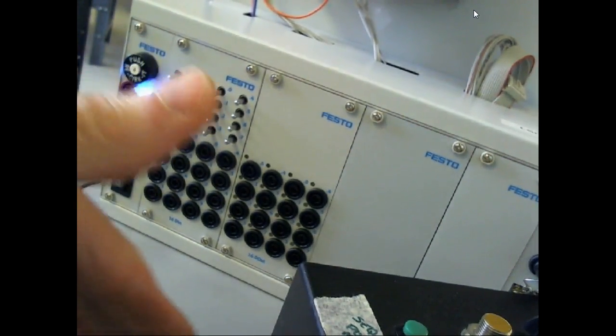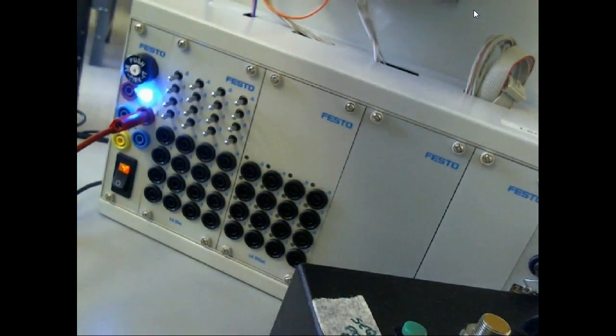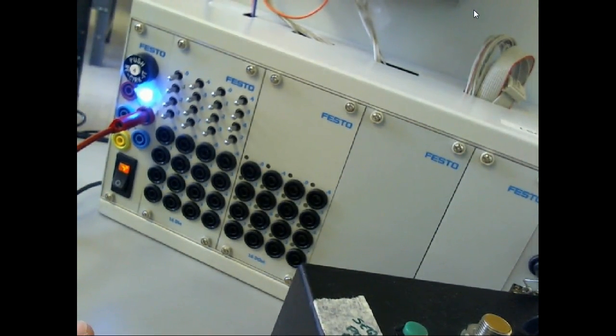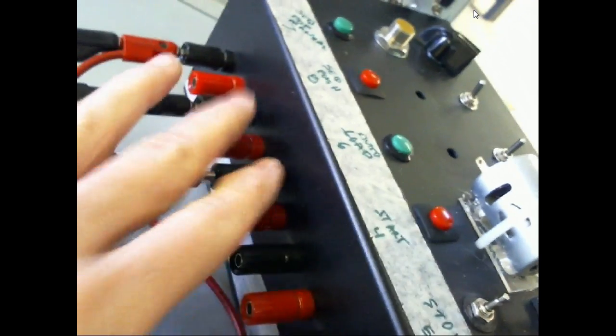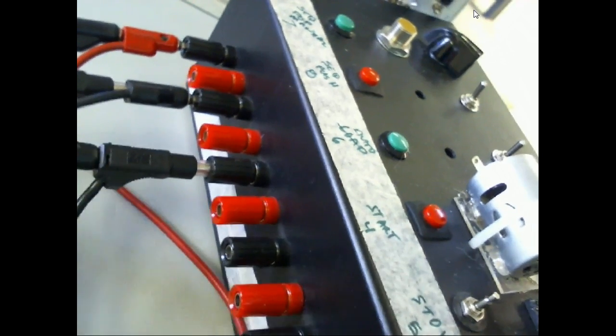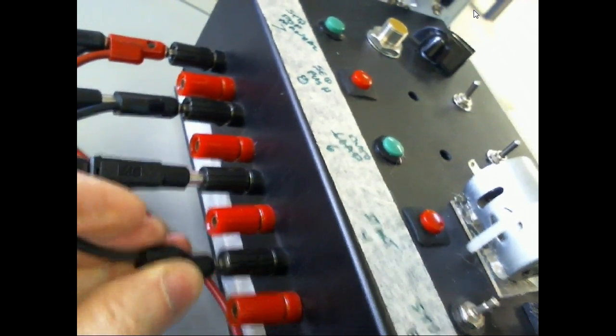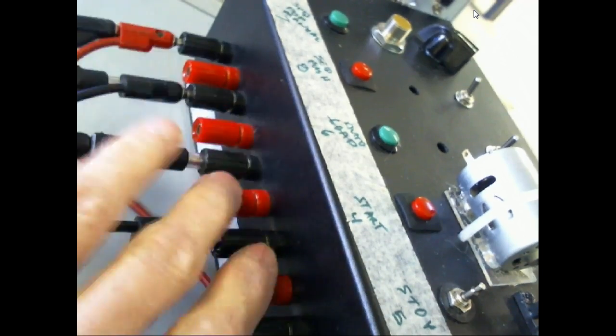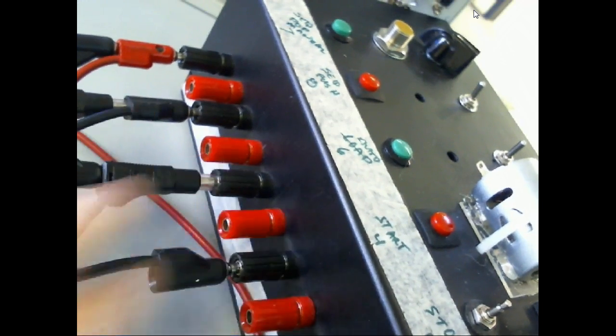So I'm running a positive common over here because my inputs are set up for what? Negative. So they're using a negative common, and over here on my input devices, I'm using a positive common. Yeah. So you can see all I'm doing is taking the jumper wires here and just jumping the commons, or the black, but it doesn't make any difference. It's just that you would have to keep it. So I could use the reds just as well on the switch of the common, right? You understand that? It's just I'm going to have to be consistent down through my line.